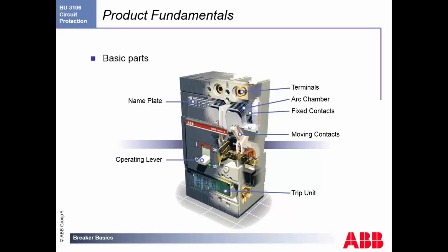And finally, we have our trip unit, which you can think of as the brains of the unit. This allows you to set your trip curves, your trip levels, your current levels, time delays, and all other parameters that you want to put in the breaker.